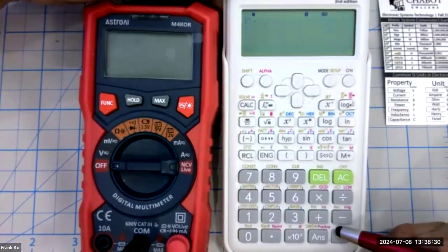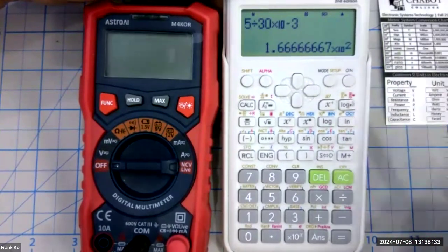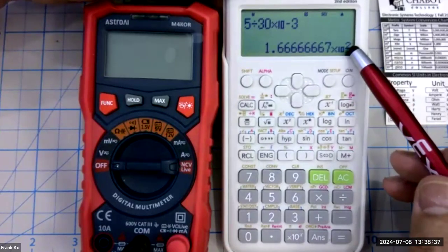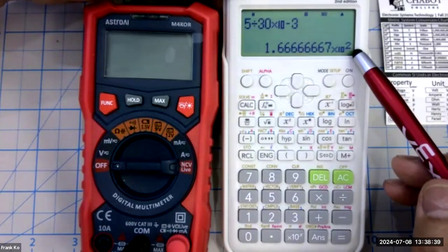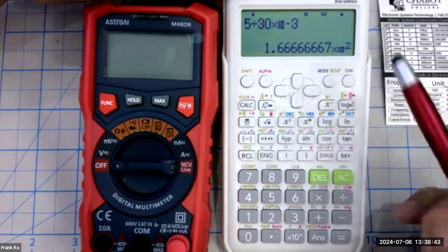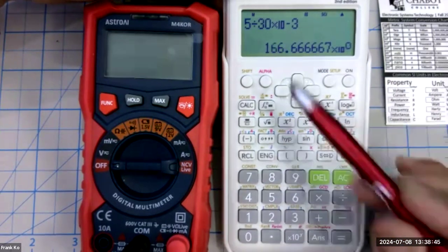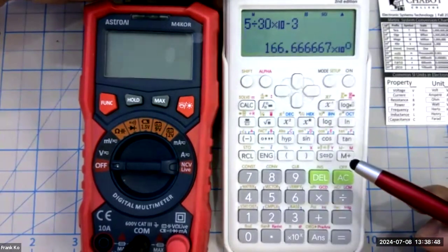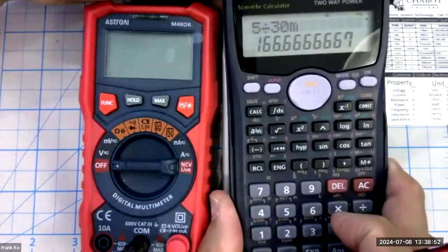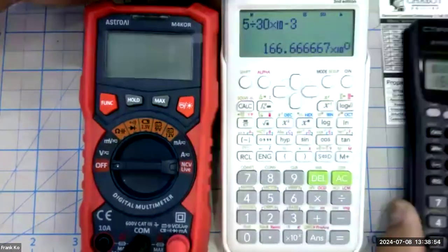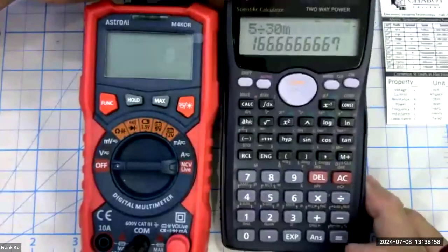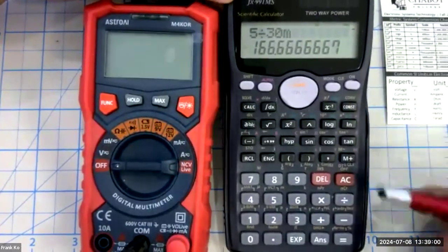And then you hit equals, and lo and behold, you end up with some scientific value, which is useless because, again, any 10 power over here that is not a multiple of 3 is scientific notation. So we want to hit our engineering key. So we touch engineering, and voila, we end up with 166.67 ohms, which is the same result as what we had previously calculated here.